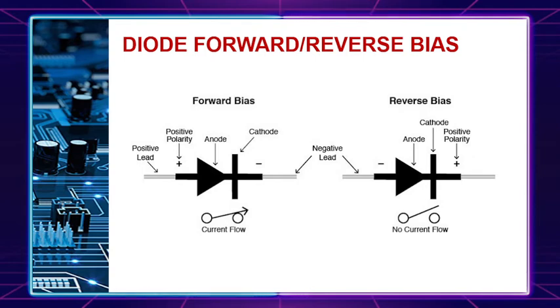The diode symbol's arrow points against the direction of electron flow. Reason: engineers conceived the symbol and their schematics show current flowing from the positive side of the voltage source to the negative. It's the same convention used for semiconductors that include arrows. So arrows pertain to direction. The arrow points in the permitted direction of conventional flow and against the permitted direction of electron flow. So that's how we differentiate a forward and reverse bias.